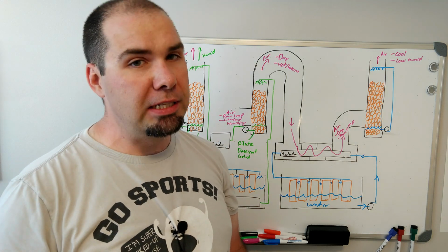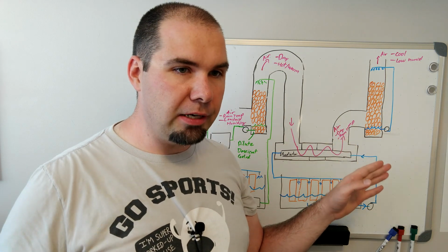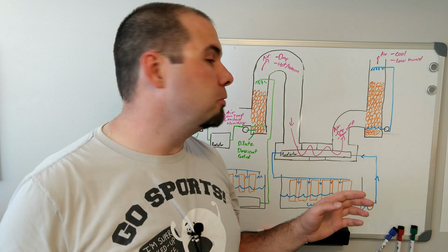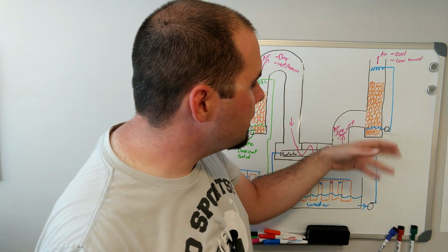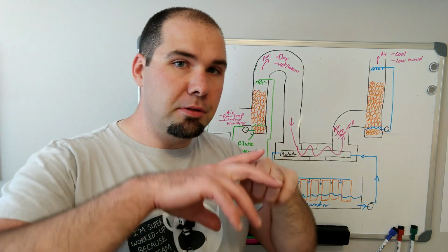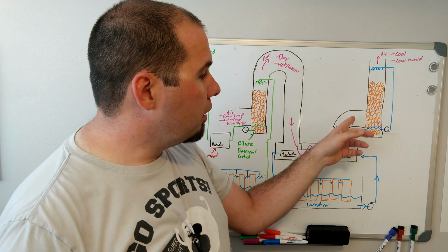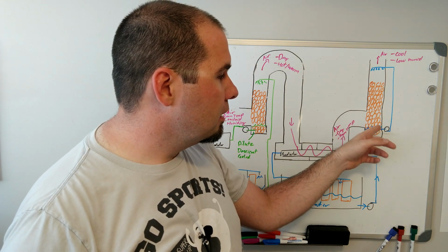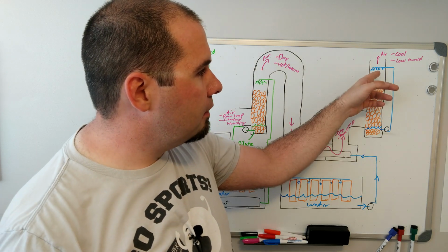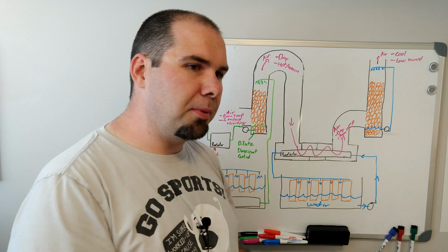And the explanation was really good. Essentially, if we have room temperature air with, say, low to medium humidity, or even high humidity if you're by the ocean, for instance, you run that in through this tube chamber with all the surface area, with this water spraying down so that there's lots of surface for that water to evaporate. What you get is the air being cooled and you get high humidity out. So cooled air but high humidity.